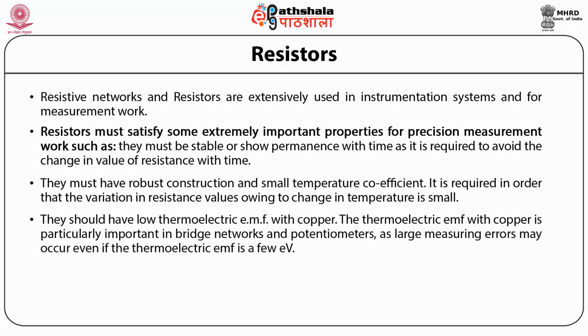They should have low thermoelectric EMF with copper. The thermoelectric EMF with copper is particularly important in bridge networks and potentiometers, as large measuring errors may occur even if the thermoelectric EMF is a few microvolts.